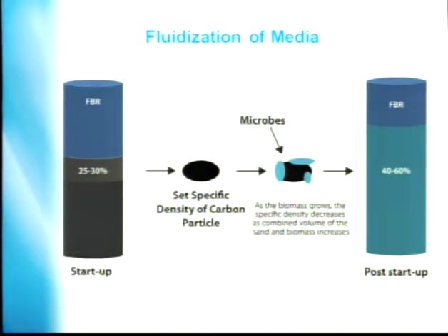In this case, I'm talking about a media which is carbon, activated coconut shell-based carbon. We could also use sand, and there are different reasons why you do that. I'll talk mostly about carbon today, just as an example, but it has a set specific density, mass over volume. And as a microbe attaches onto it, you get a lot of microbes. They're mostly just water, so they don't really add any mass because the particle itself is in a water medium. But the volume expands, so the specific density actually decreases, and what that allows is that the bed will biologically grow, and it expands to about 40 to 60%.